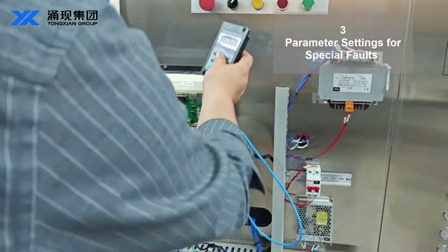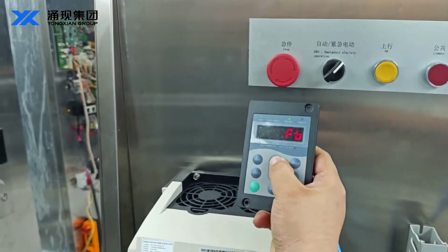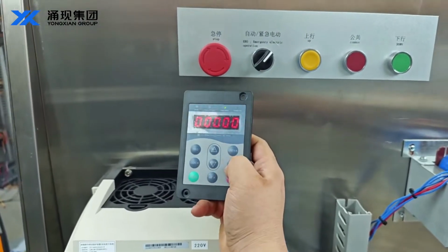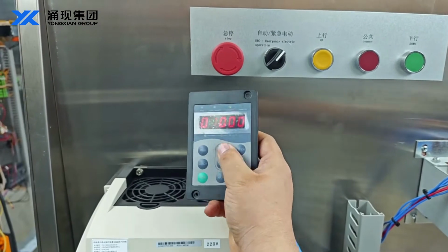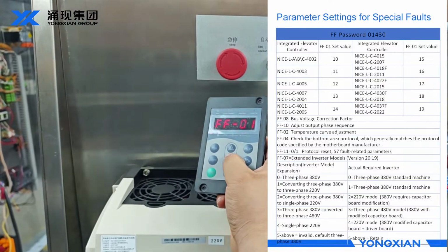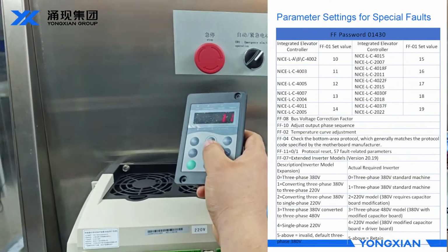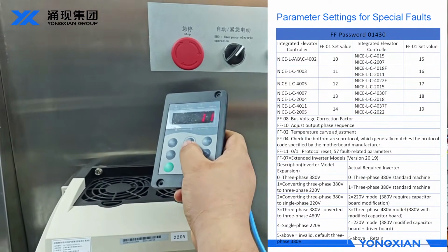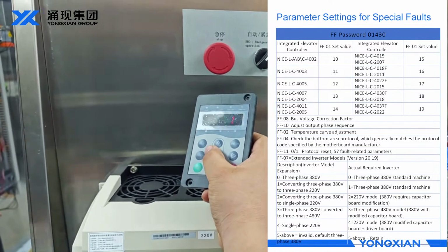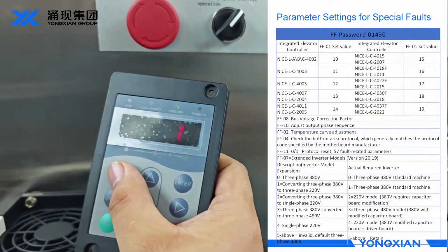Now let's look at the test tool. First, we need to enter the code menu and input the password 1430. FF01 is the model setting for the integrated elevator controller. Usually we set it according to the barcode.